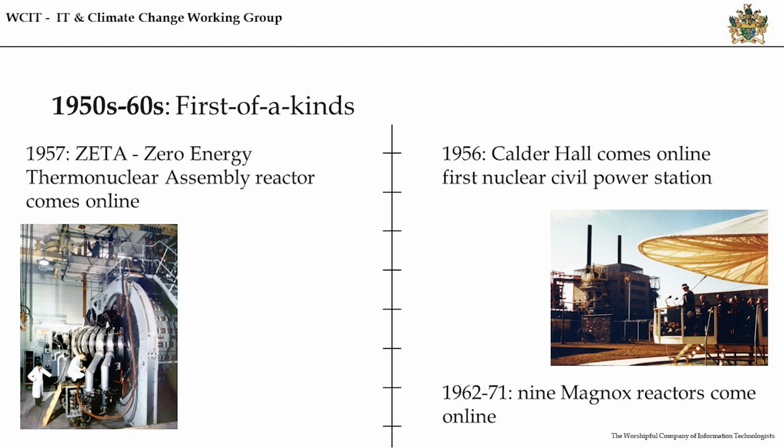And the design of the Magnox reactors was integrated from the Windscale piles. So the Magnox reactors, whilst creating electricity, also had a secondary function to make plutonium for the bombs. So that's why the design is as such. It uses gas as a coolant, it uses uranium oxide as fuel, and that's kind of put us on our path today for our nuclear reactors.